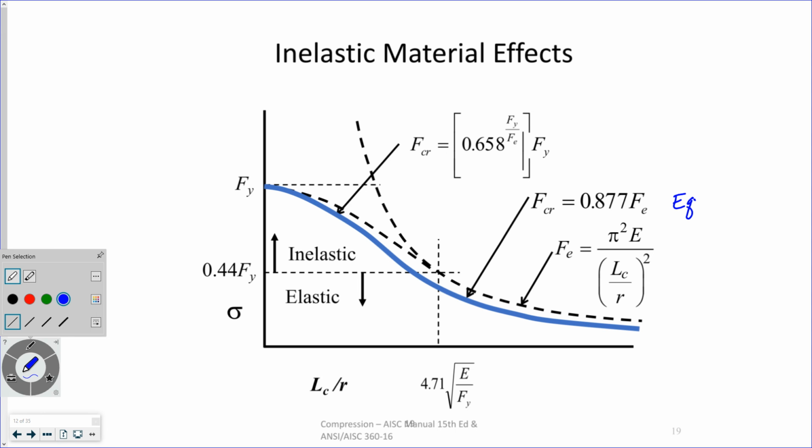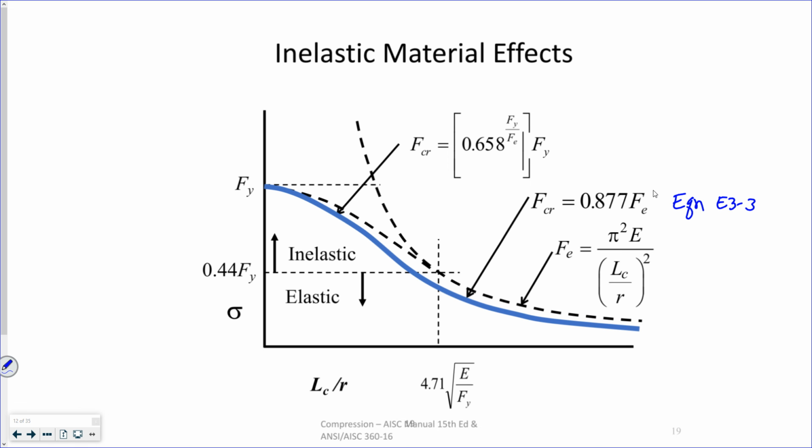It is equation E3-3. This is for inelastic buckling, E3-2. And you can see how that blue line compares to the theoretical. We've reduced our stress ever so slightly, because of testing. It's not perfect.